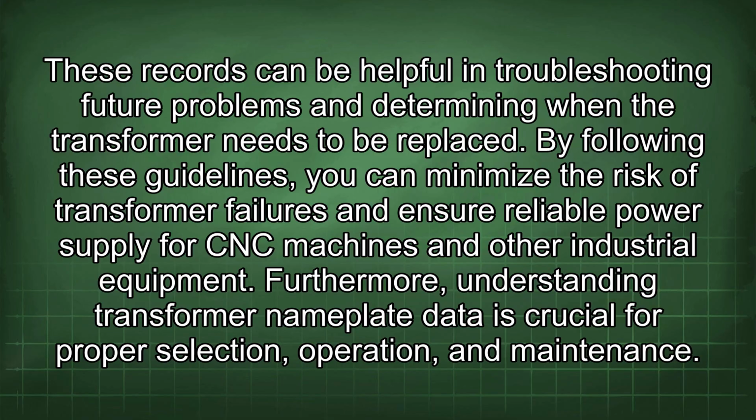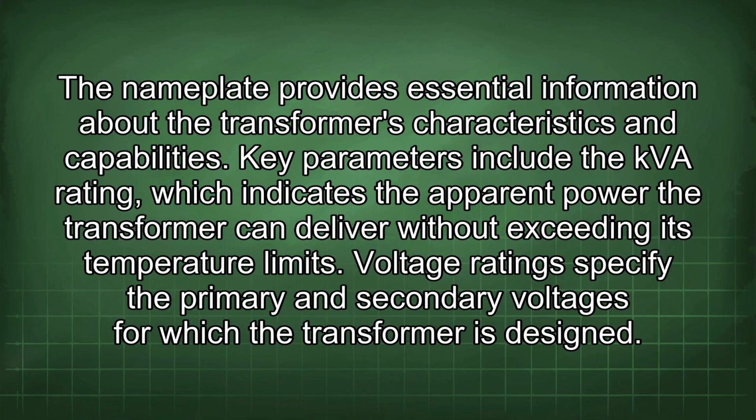and other industrial equipment. Furthermore, understanding transformer nameplate data is crucial for proper selection, operation, and maintenance. The nameplate provides essential information about the transformer's characteristics and capabilities. Key parameters include the kVA rating, which indicates the apparent power the transformer can deliver without exceeding its temperature limits.